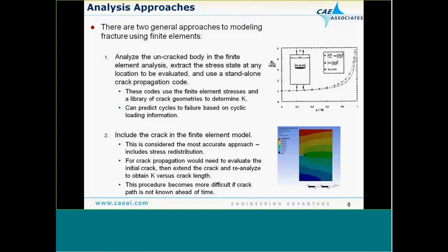ENCODE, which is in the family of the ANSYS programs, is a fatigue program that also has a module that will do this as well. But essentially, these codes have libraries of standard different crack types, like a center cracked plate under tension load, or an edge crack, or different 3D cracks. They have a library of solutions for K1 and stress intensity factors.